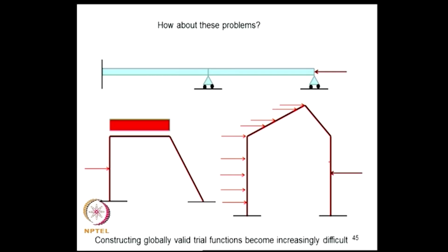This situation we have encountered when we started discussing application of the finite element method for vibration problems. So what was the remedy at that time? What we did was, a structure like this is discretized into elements, and the nodal displacement values were taken as degrees of freedom, and the field variables within an element were interpolated using the nodal values of the degrees of freedom at the nodes, and then we formulated the mass and stiffness matrix.